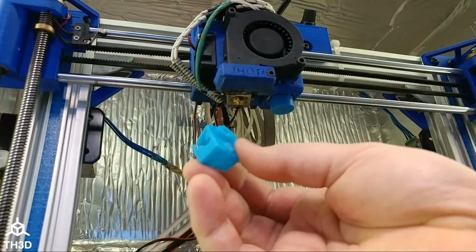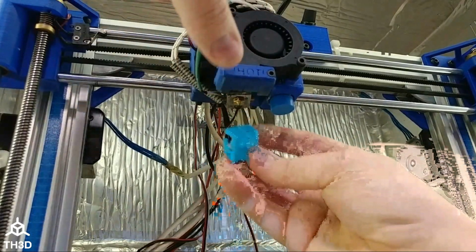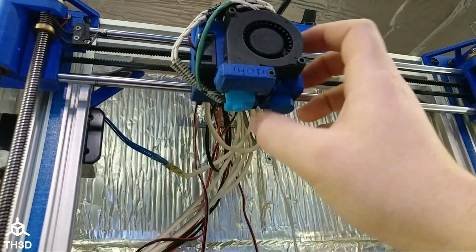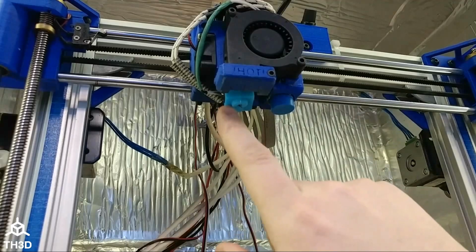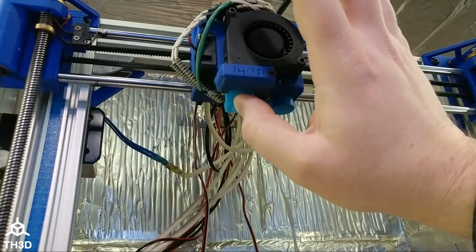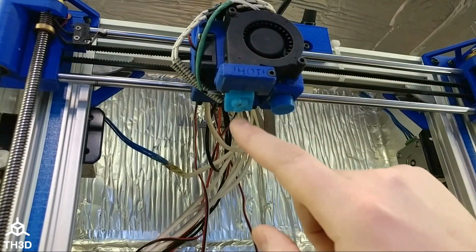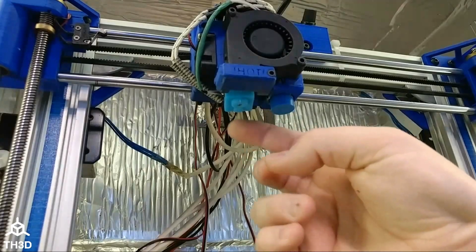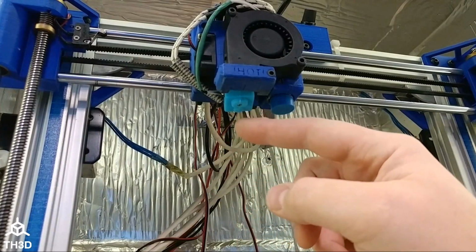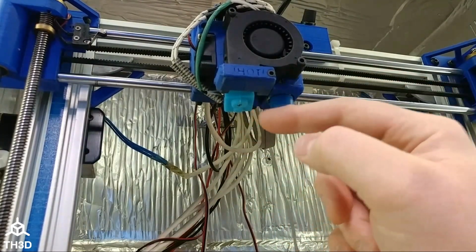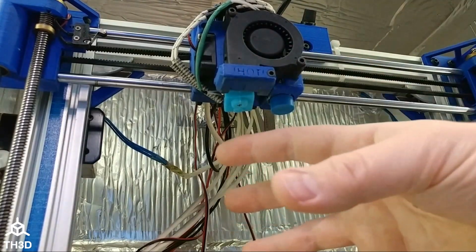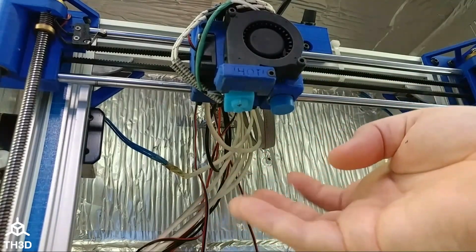But these are great because you literally just take them and put them up on the block like so. And you can do this while it's cold. But you can see here just a little tip of the nozzle poking through. So what this is going to do is help maintain stable temperatures and insulate the block from the air coming off your layer fan. So I'm going to let this settle out temp-wise because I want this sock to heat up.